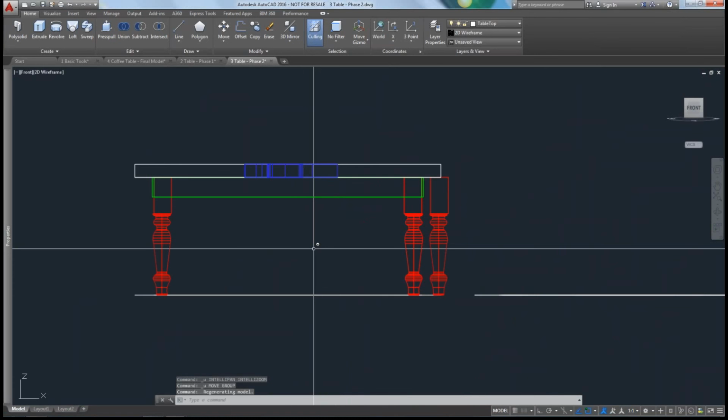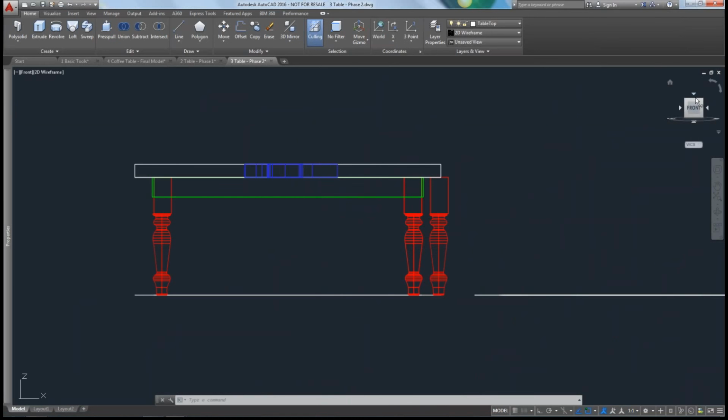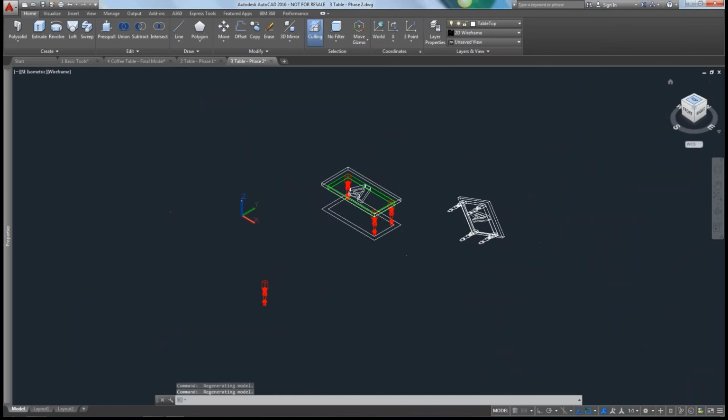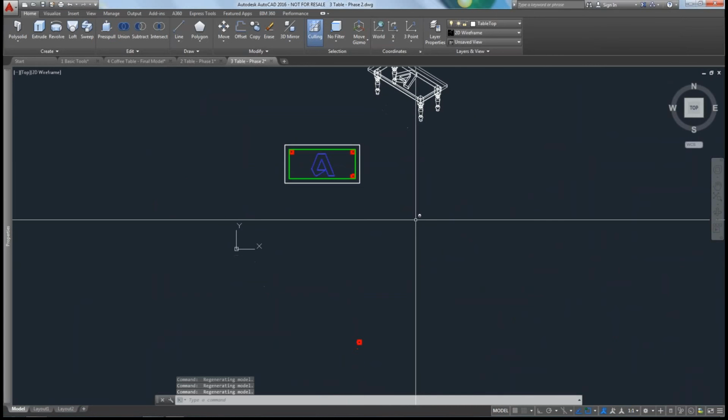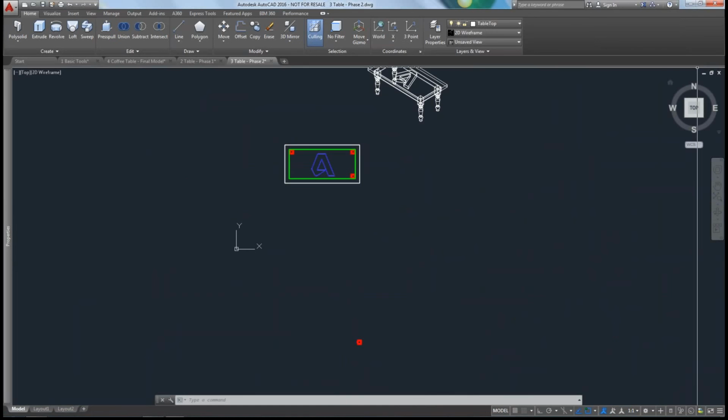you can see when I was in the isometric, it looked like it was down and to the left. It was actually, looking at it in the front view, down and to the right, or top view, again, down and to the right. You just want to be able to make sure you have those points. So in a 3D model, sometimes it's almost better to be moving objects in an isometric view so you can have that proper view. Again, make sure that you use the proper O-snaps. Okay. And I think there's a question about how to measure between 3D objects.